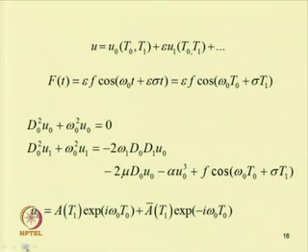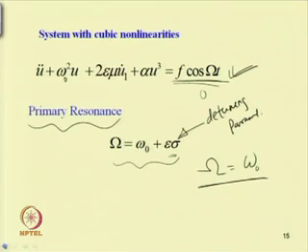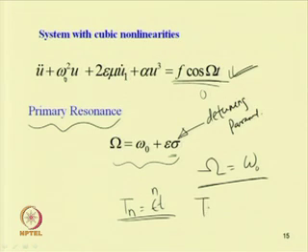or one can study this system by using some perturbation method. So, as we are considering a weak nonlinear system, let us take first u equal to u 0 plus epsilon u 1, functions of T 0, T 1. Here the forcing function f(t) we have taken as epsilon f cos of omega 0 t plus epsilon sigma t, and as we are using the method of multiple scales for our analysis, this T n, that is the time scale, is taken to be T n equal to epsilon to the power n t, where epsilon is the bookkeeping parameter and t is the original time. So, we have different time scales like T 0, T 1, T 2 and higher order terms.